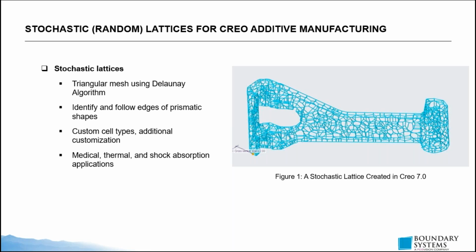One of the enhancements that's made to stochastic lattices as a whole, Voronoi or Delaunay, is that historically in Creo 6, sometimes the stochastic lattice did not always see and obey the hard model edges you had. So if you hadn't added any model edges, sometimes the stochastic lattice would not create a beam in that location, for example. Versus now, just as a baseline, Creo 7 stochastic lattices will respect those hard model edges, right?